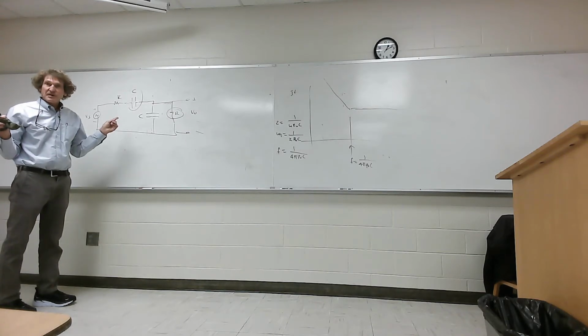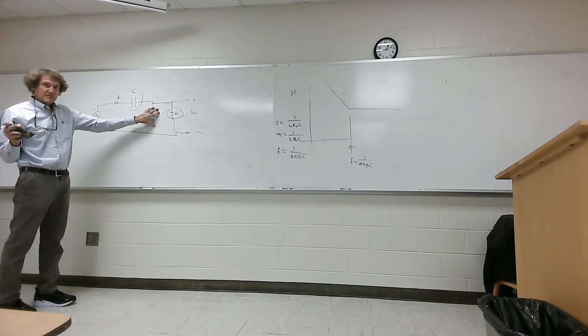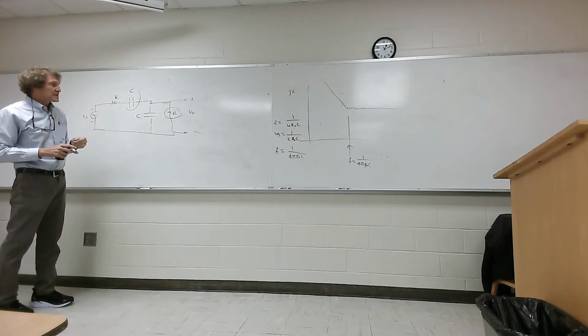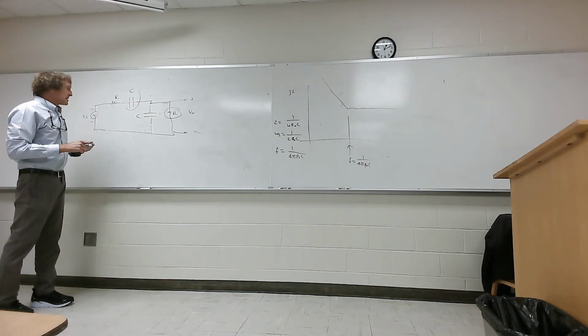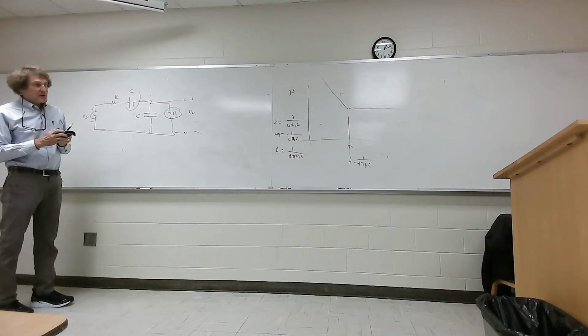Have you done these filters, this kind of stuff? Now, I could put 2 inductors there too, right? That would not pass DC. It would be a short here if that was an inductor, right? At DC. But there would be a band that passes, but this is an odd type of filter because it doesn't have a clear inductance and capacitance. You actually have to write the output versus the input and then plot the thing for some of these filters. Just making you aware of this.